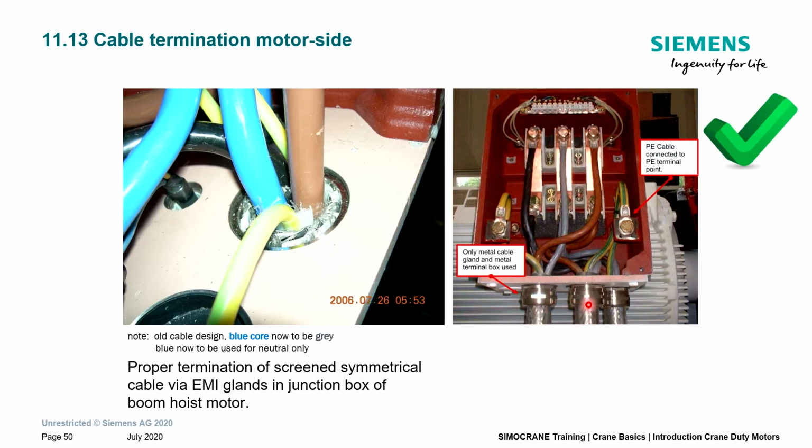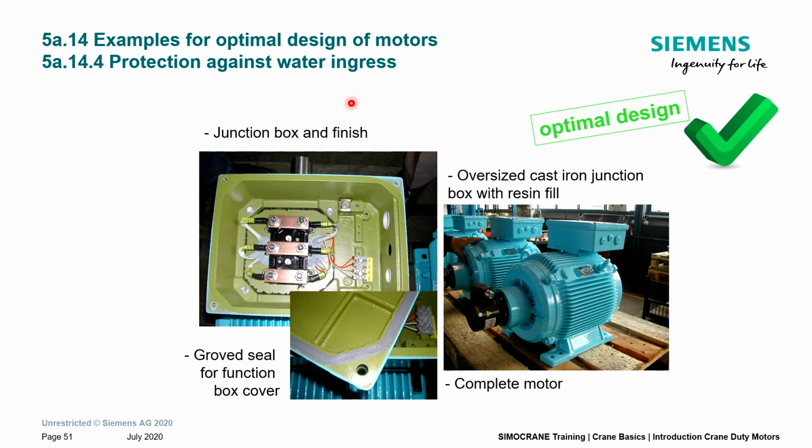Nice design for a junction box. It's a great arrangement. The most important material for outside is of course cast iron. I have shown you the aluminium type previously. Aluminium is not suitable. Here you can see proper cable box installation, where the power cables arrive at the terminal box, and they are connected and screened via, let's say, a cable gland. And the cable gland is connected with the terminal box. And here you can view from inside, where you can see the screen of the power cables, really well connected and well fitted with the terminal box. That means on both ends of the power cable.